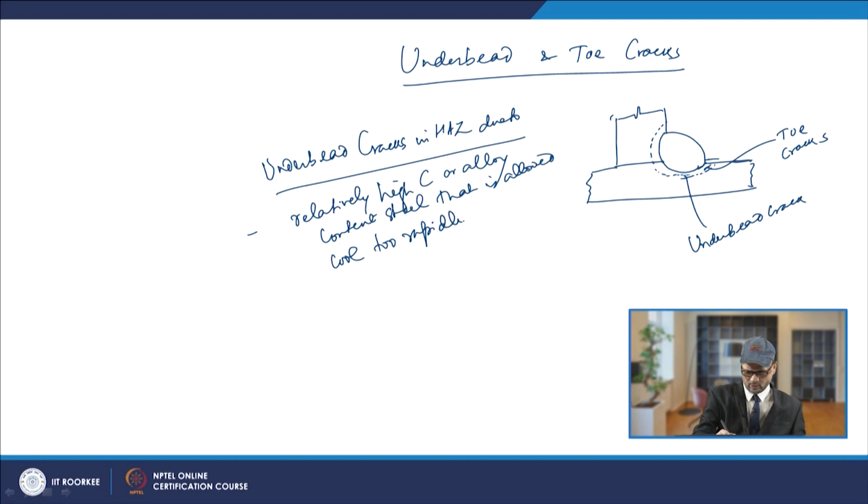In that case there is a chance of formation of undesirable structures, and that leads to the formation of these underbead cracks in the weld.